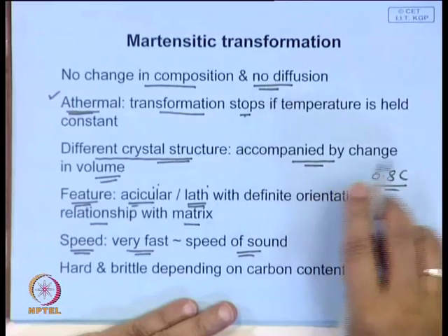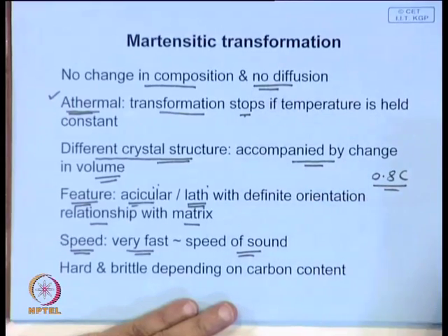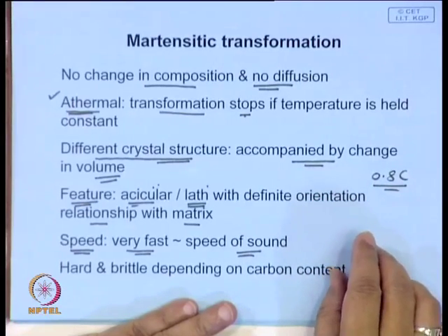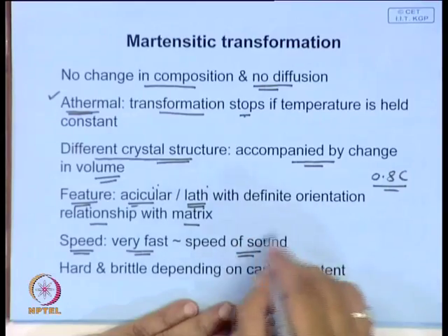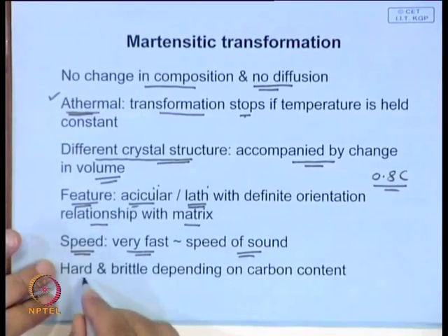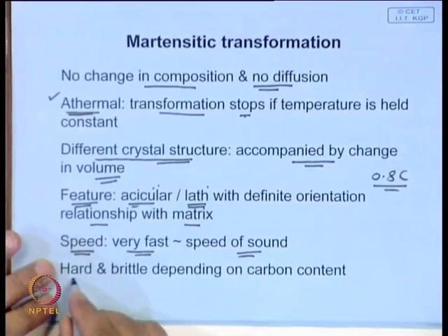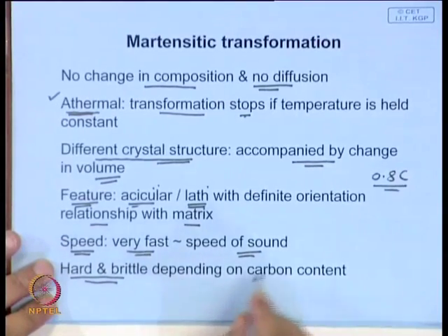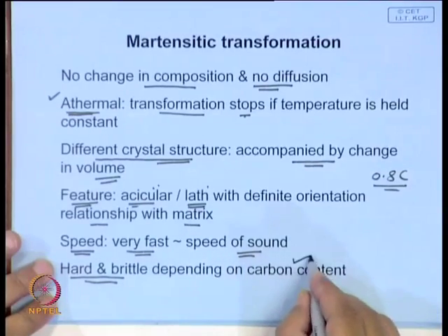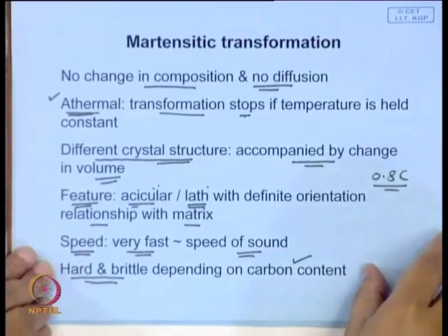Therefore, when the martensite forms, if it is possible to keep a microphone, you can amplify it and hear the noise. And since you are keeping so much carbon in solution by force, it is extremely hard and also brittle, and the extent of hardness and brittleness will depend on the carbon content it has.